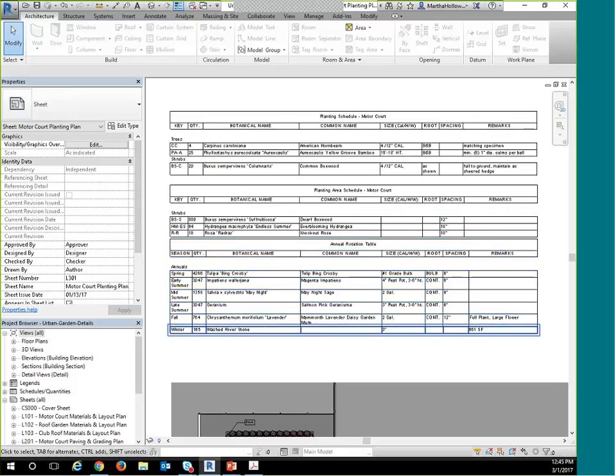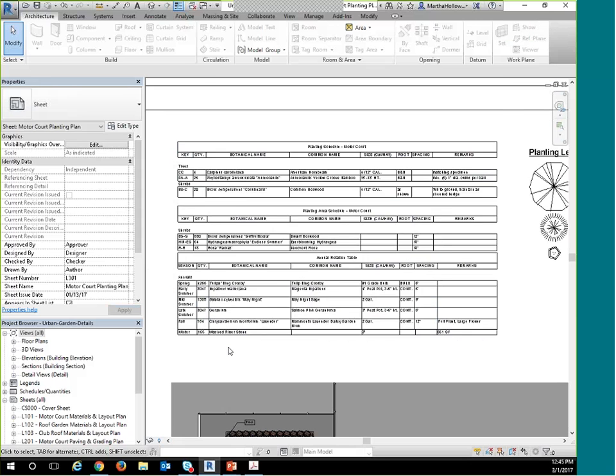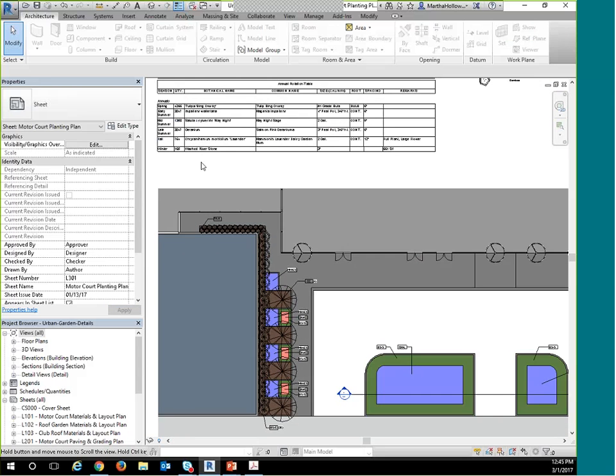And the way we did that, again, this is our workaround. You might find some other better ones, but what we did was we actually just put in a whole bunch of floors on top of each other because it really didn't matter how thick these floors were because what we wanted was this information.